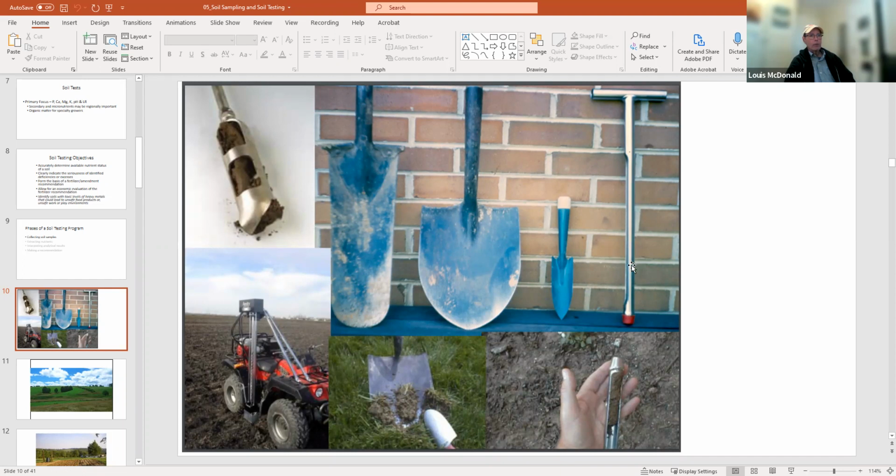This is the ultimate way to collect the soil sample, especially over large areas. And they come in different lengths. It's called a soil probe. They also make them with little handles on them so that you can eject the core that comes out directly into a bucket. I used to have some of those, but I loaned them out and they didn't come back. That's how much fun they are to use. You just sort of shoot a core into a bucket and go on with your day. So here's one in use. The tips are designed so that it doesn't compress the soil into the core so that it comes out easily.